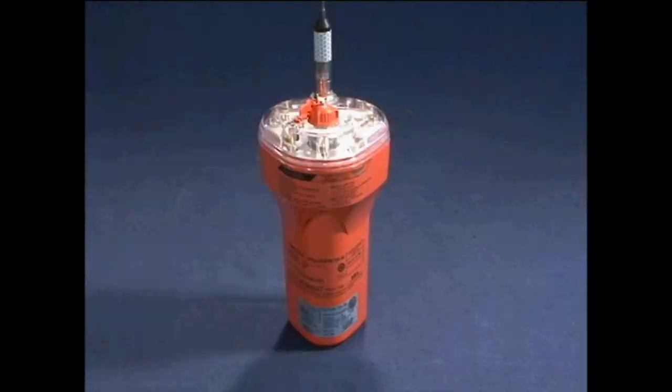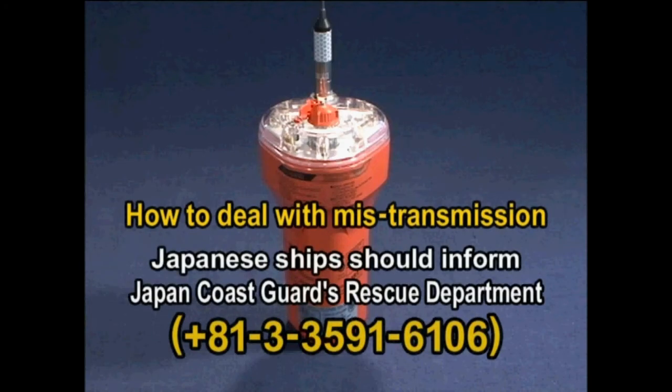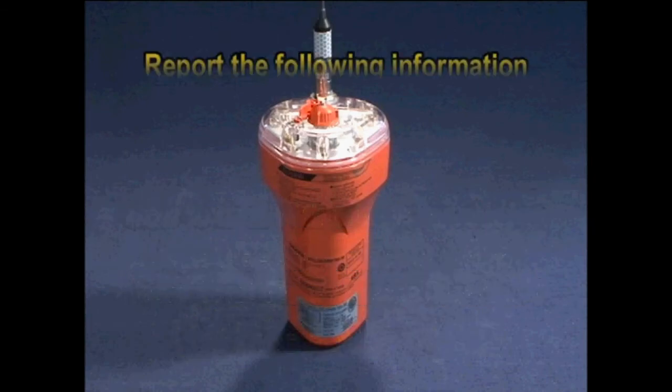If a distress signal has been transmitted by mistake, corrective measures must be taken immediately. First, stop transmitting the distress signal. Second, report to the appropriate search and rescue coordination center. These are determined by vessel nationality. In the case of Japanese ships, a report should be made to the Japan Coast Guard.